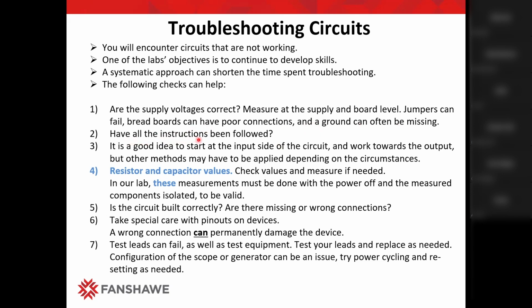Have all the instructions been followed? Sometimes you have to retrace your steps. It's a good idea to start at the input. Okay, so start at the input and work towards the output. Depends on what kind of circuit it is. There are two basic concepts. One is signal tracing, and the other one is signal injection.